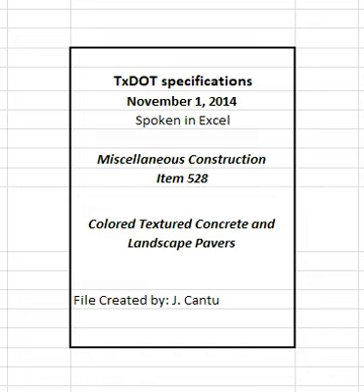3. Construction. 3.1 Colored textured concrete. Prepare for approval a 9 square feet, 3 inches thick specimen for each color, pattern, and texture required before beginning work. Prepare the subgrade, base, or both in accordance with the plans and pertinent items. Place and screed concrete to the proper grade and wood float to a uniform surface, in accordance with Item 420, concrete substructures. Apply colorant in accordance with the manufacturer's recommendations.